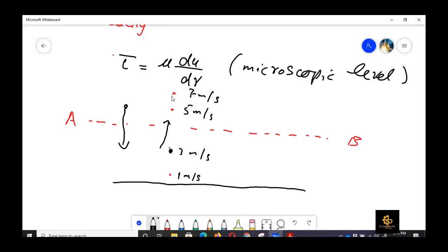But what happens in the turbulent flows? Because in turbulent flows we have got some kind of eddies, or vortex we call it. So in turbulent flows, these translations between the layers are at a much higher rate, right? So if there were only one or two translations in the laminar flow, maybe in turbulent flow there would be 10 to 20. So there would be some contribution from this particle translation due to these vortices. There would be another vortex that would be taking high speed fluid to the pipe surface.